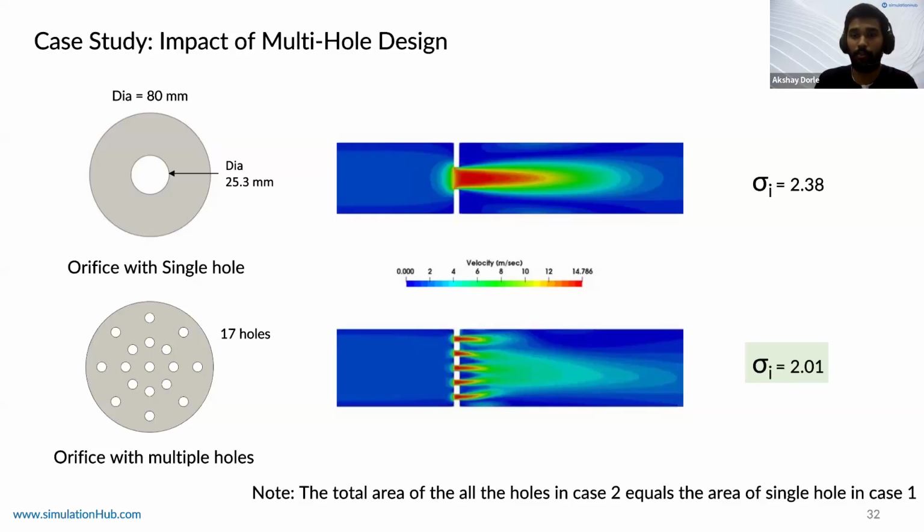If you go with operating sigma, the operating cavitation index, it becomes very tough to judge because it will be the same and you cannot get insights. But the incipient cavitation index will give you that insight, whether design 1 or design 2, or any number of designs, which one is better. So yeah, just taking that point that Praveen mentioned.